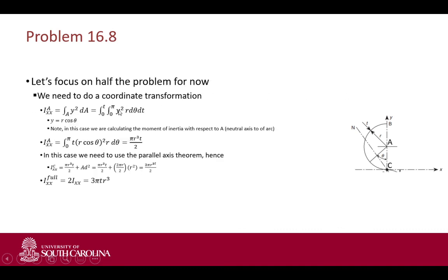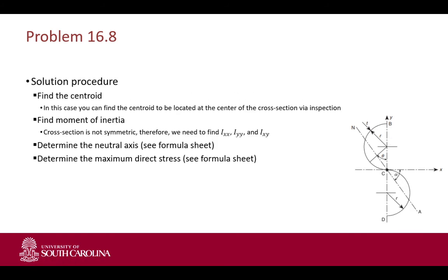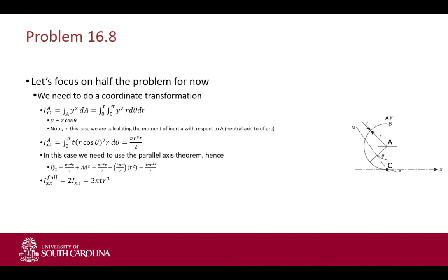And then we can do that. In this case, for the A section, we know the cross section over A. Again, if you do the full integral, we do a small coordinate transformation. We go from x and y to r, d theta. We calculate the moment of inertia. Basically, you can memorize that the moment of inertia of a half circle is equal to pi multiplied by radius to the power 4 over 8. And then we apply the standard terms, and then we multiply by 2 because we have two of these. So we go from a complex problem that might seem intimidating to the basics that we understand as cross sections around their own centroid or own center, and then we add a standard term to translate, and then we know we have a top and bottom, they're symmetric, so we can add that together.